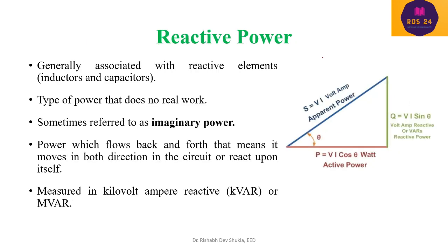Reactive power is the type of power that does not have any real work. Sometimes it is also called the imaginary power. It is also defined as the power which flows back and forth, that means it moves in both directions in the circuit. So for a purely inductive circuit, the total power consumed in the circuit is zero.